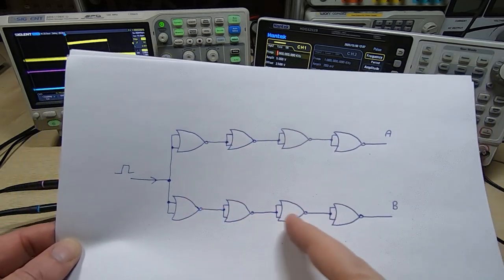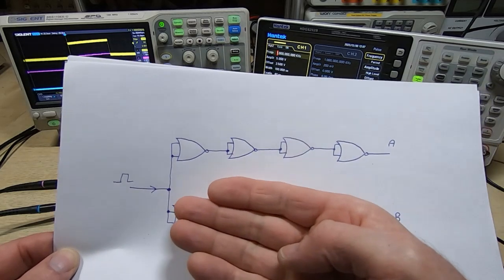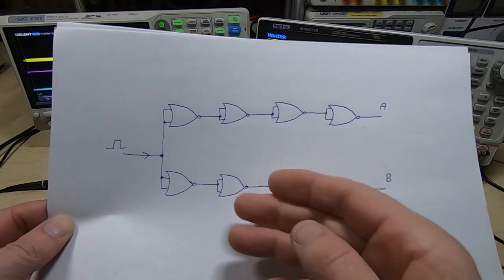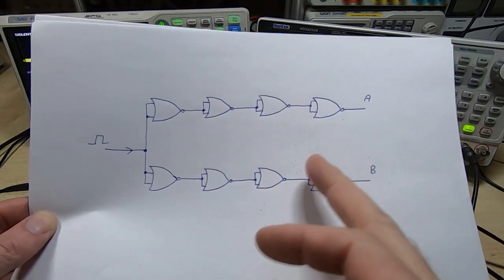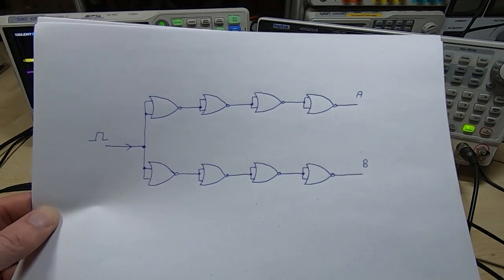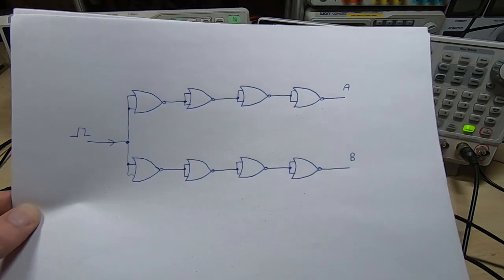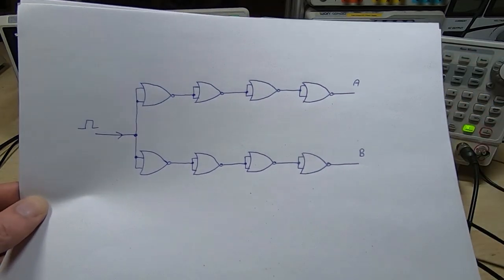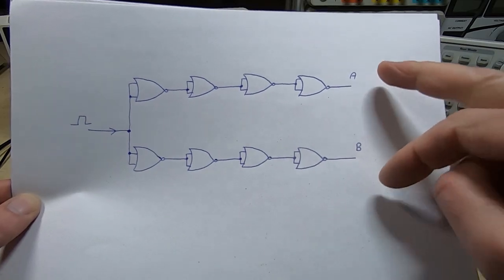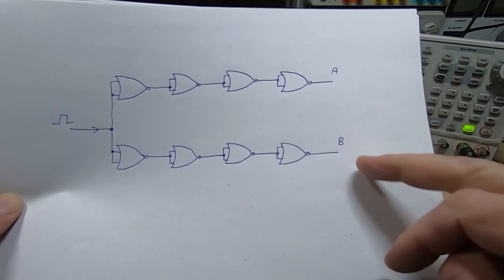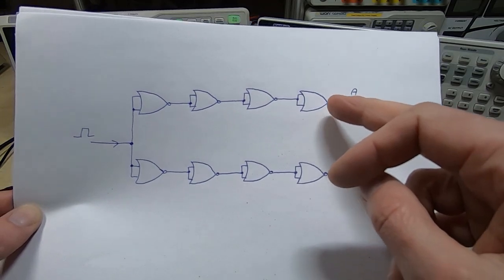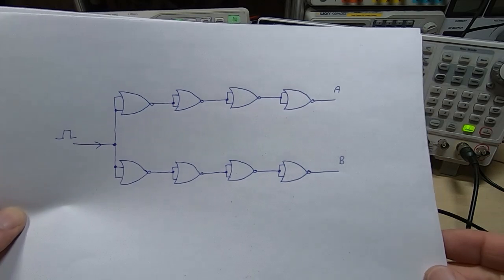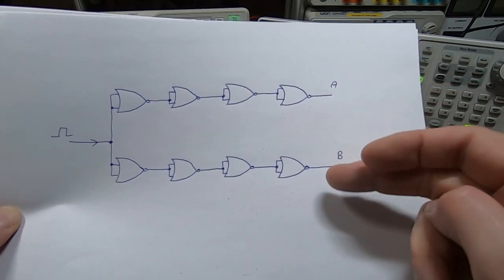What this is meant to represent are 2 separate chains of gates, one terminated at A, one terminated at B, and it's just so we can examine 2 different IC performances at the same time. I'm not suggesting that you set up a circuit like this because you would end up with a race condition, but what we can do with this circuit is look at the output at A and B and see what impact a failing IC has on the relative timing of the 2 signals, and then I'll explain why this is